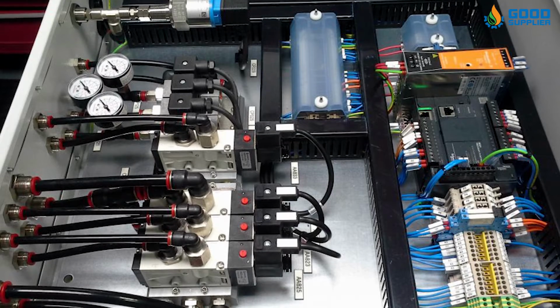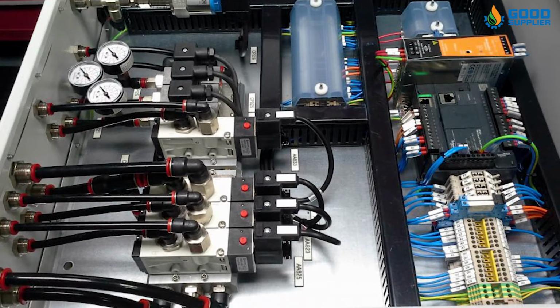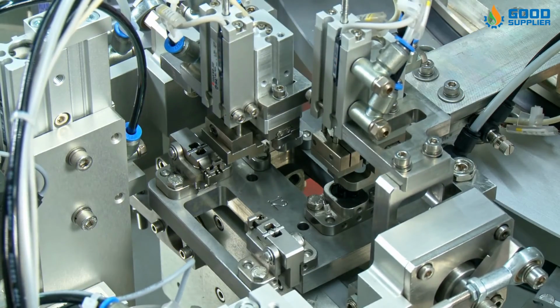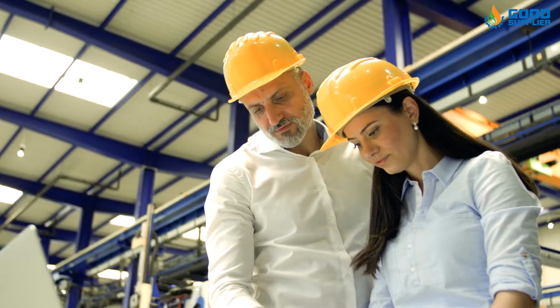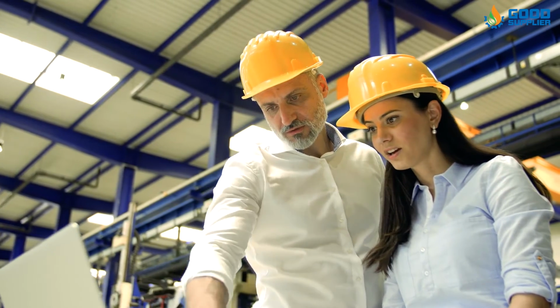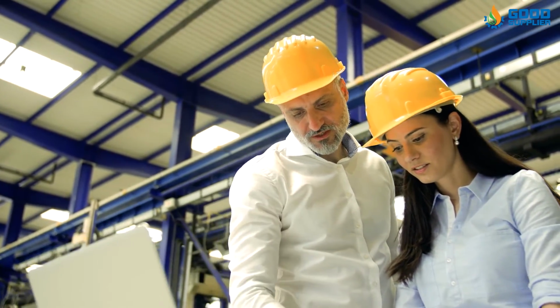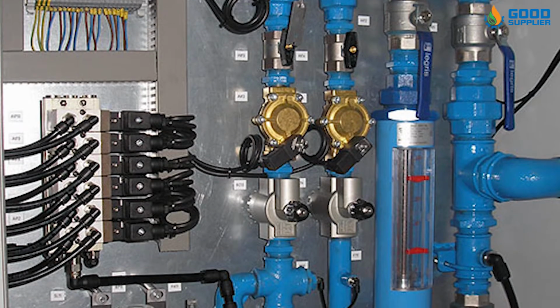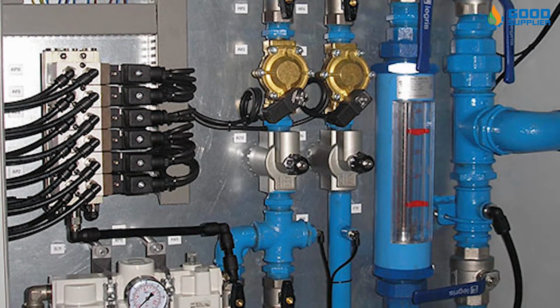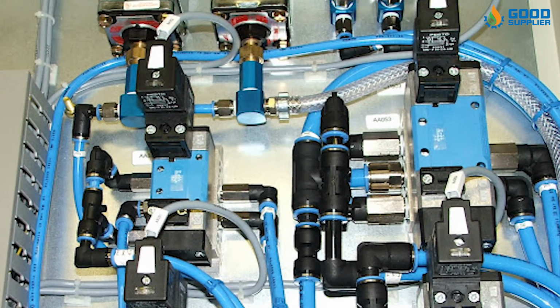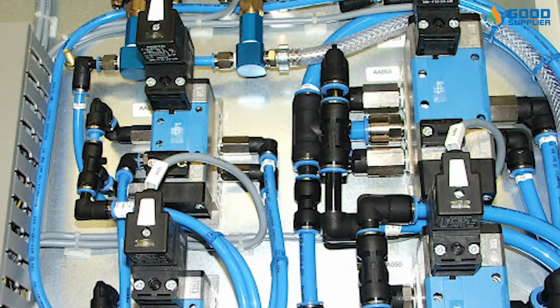Directional control valves are vital in any pneumatic circuit, directing or blocking airflow to control the speed or sequence of operations. One method of classifying directional control valves is by the flow paths under various operating conditions. Important factors are the number of possible valve positions and the number of ports and flow paths. Now, we will see 4 basic configurations.